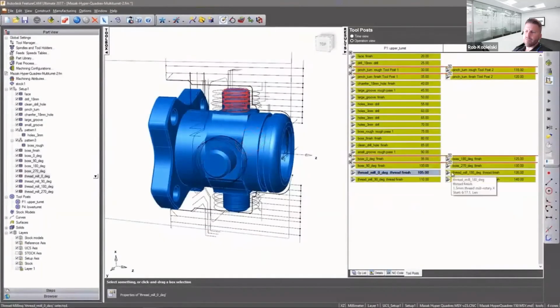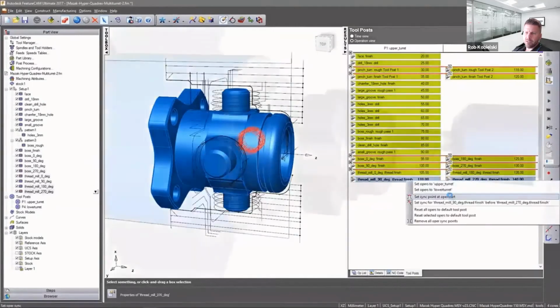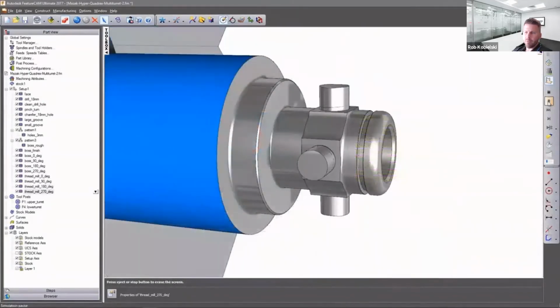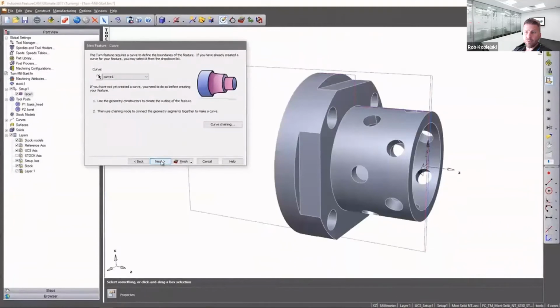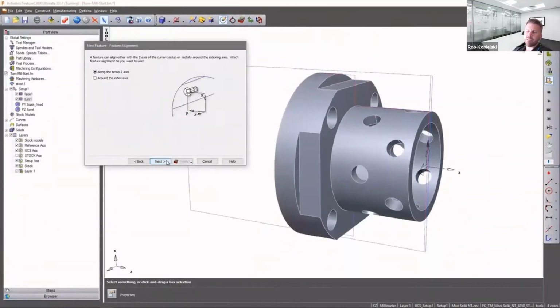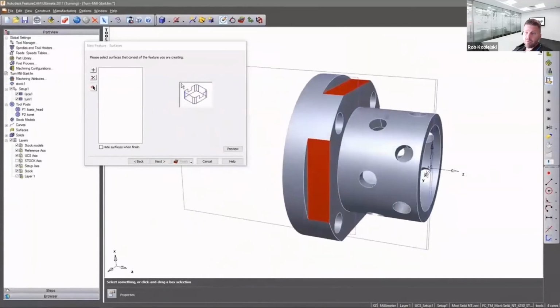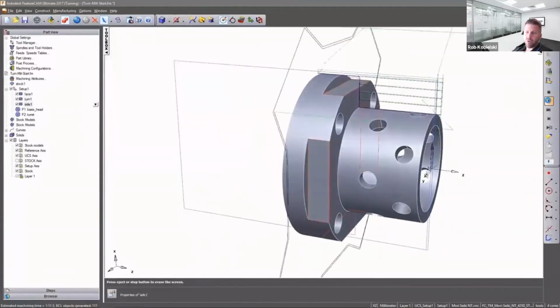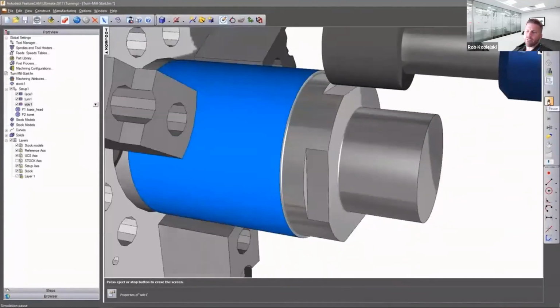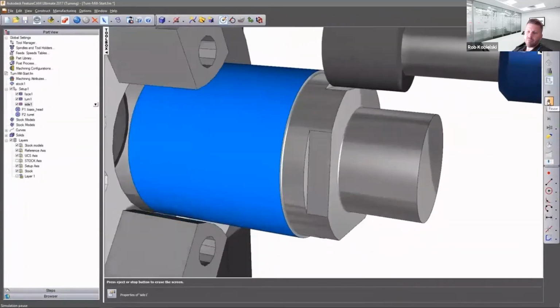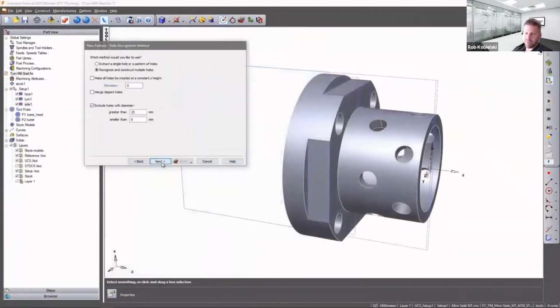Productivity is maximized for multitasking turn mills using pinch and following turning to double the feed rate or double the rate of material removal with automatic synchronization of operations. Pinch milling is also supported by using drag and drop synchronization of operations in between turrets and spindles to reduce your overall cycle time.